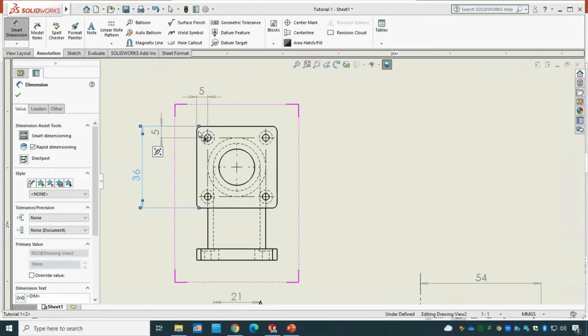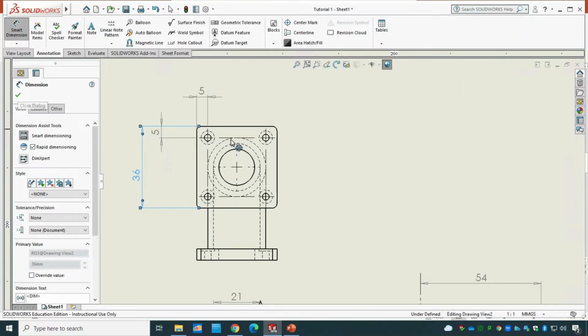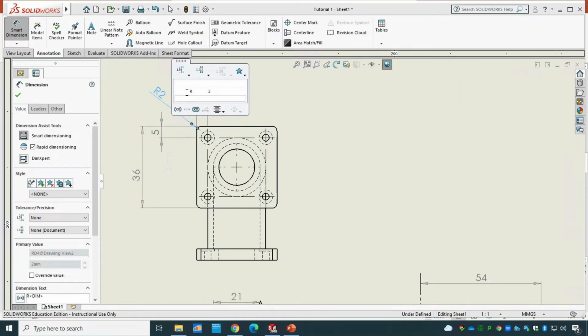And what I will have here, I can make for the fillet there, that's basically R2, and I have 4 of them here. Or what I can do, I can either use the automatic or the manual. So hopefully now you remember. Let me quickly do that manually here. That's basically I have 4 of them there, and that's absolutely fine. So that's it.